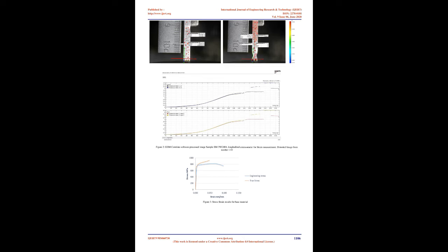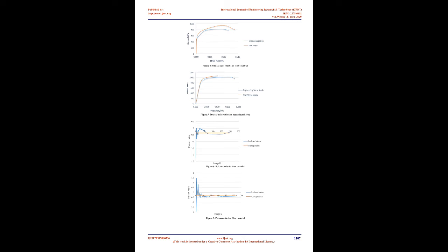Using the GOM student software version, miniature test images are analyzed. The analysis has been made for engineering stress-strain as well as true stress-strain relationships. For true stress-strain, AutoCAD software is used to examine the dimension changes given by GOM. A transverse extensometer is marked on the modeled specimen in GOM and the transverse length at each interaction point has been measured. This technique is applied on both image sides of the specimen, thickness and width, in order to obtain the actual stressed cross-section area at any instant of loading.